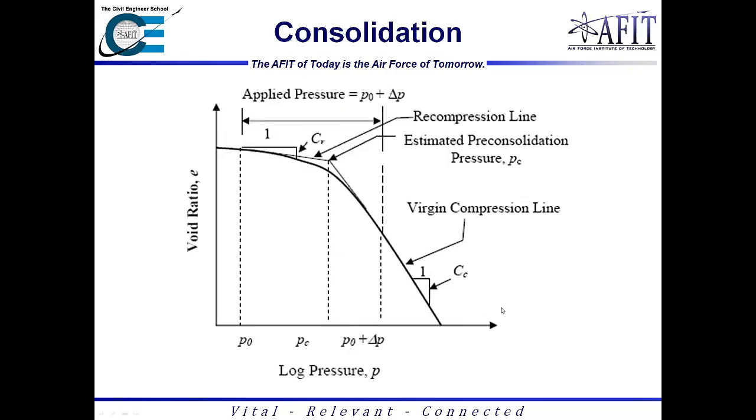And so here's kind of what we have here, a typical consolidation curve. This is actually from a consolidation test on a cohesive soil. With cohesive soils, you can think clay for this matter. The consolidation curve follows this black line right here. If you notice, we have these two tangents coming off of it. What these two tangents represent is if I took a linear approximation of this part of the curve and a linear approximation of this curve, I'll wind up at this point right here. Just for reference, this is called the recompression line, and this is called the virgin compression line. And I'll get into a minute why they're called that.